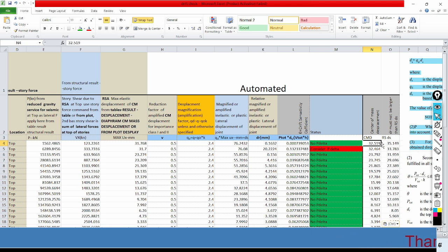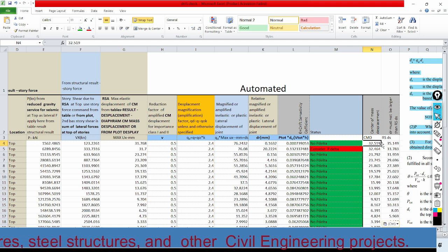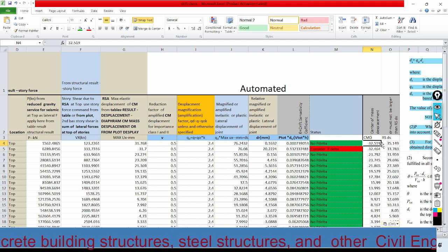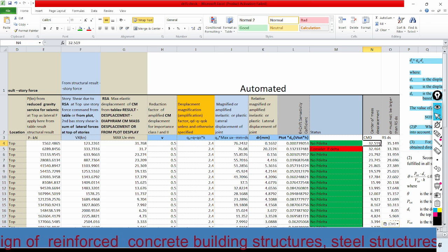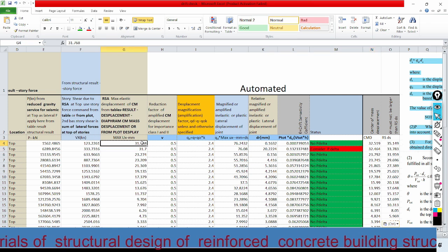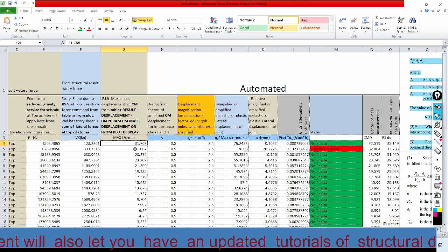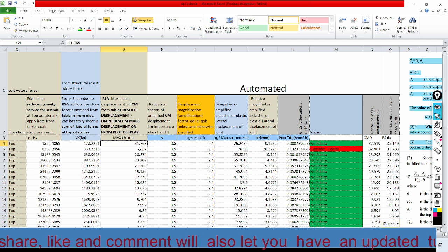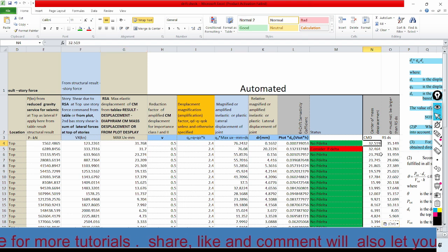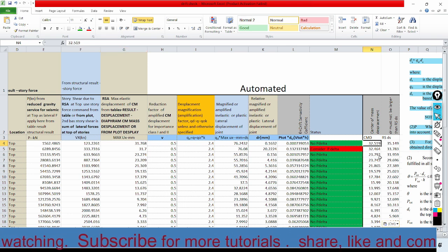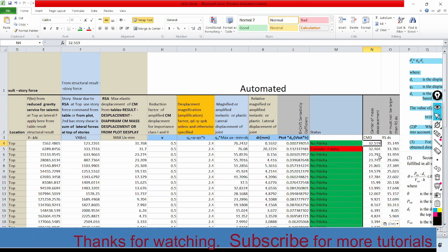That means just considering the P delta will result in higher lateral displacements of center of mass. But if we exclude the P delta, the center of mass displacement will be less, that means less than that of the model while we are considering the effect of P delta.